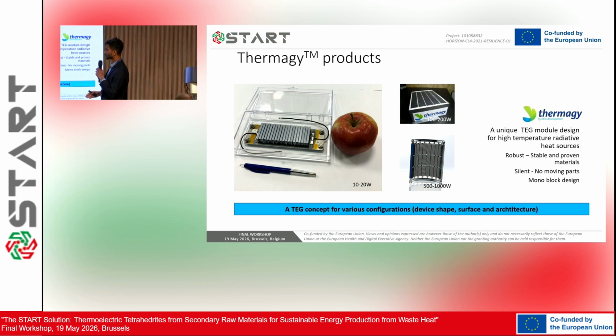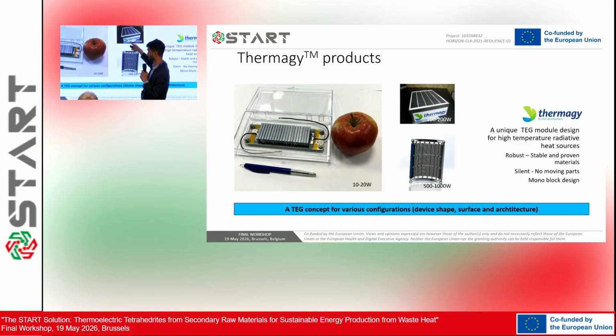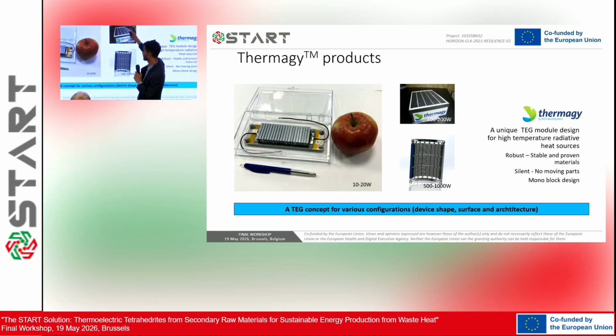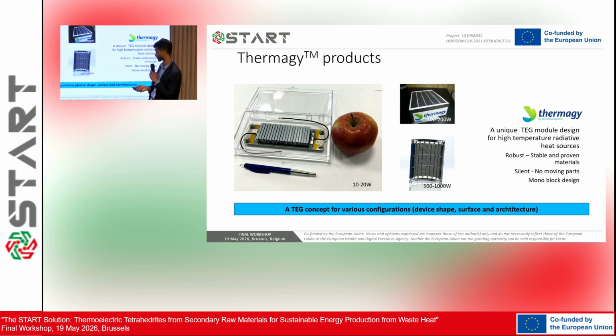This is to give you a snapshot of our most mature high temperature thermoelectric generator device. What we work on is first a unit, a 100 by 40 millimeter unit, which we called a module. And then we also look at systems where we are able to string together up to 15 such modules. This is an entire panel of thermoelectric devices which can generate up to 100 to 200 watts of electric. So that's serious power, especially in combined heat and power applications.